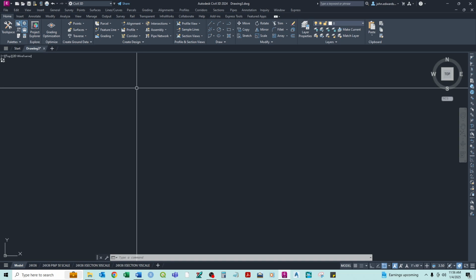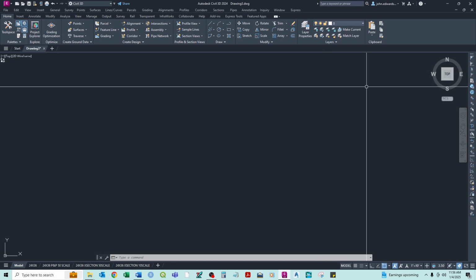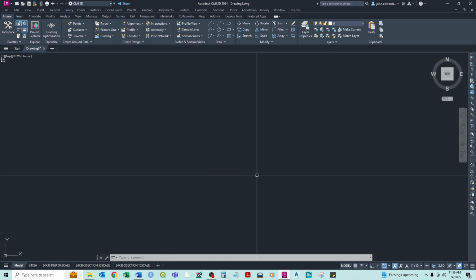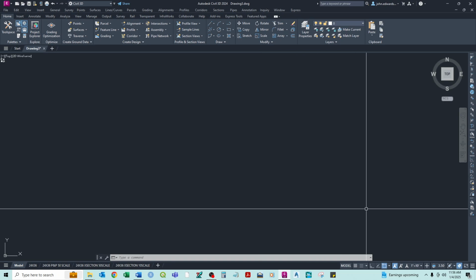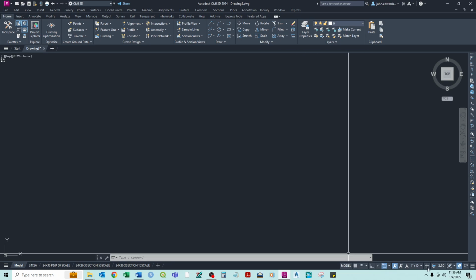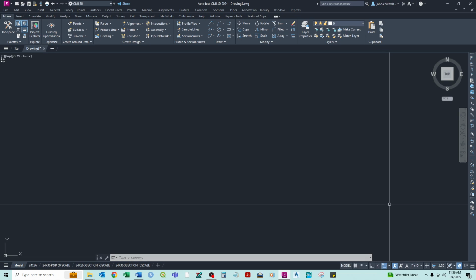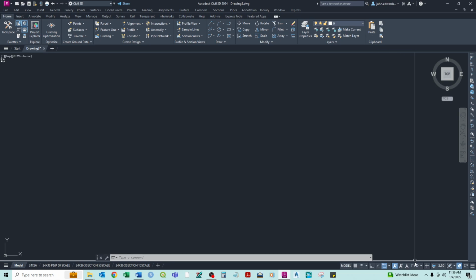To further orient you to some things, just so you're more familiar with the layout. Down here, this is another thing that will tell you model, and so it says model or paper space. The layout views, this is what we call paper space because this is going to be the printed paper. So it's almost like a print preview in that sense. There's a bunch of little buttons down here. These are mostly just random tools you can use or modes you can switch on and off, and we'll go through all of these. You have your drawing scales and different things.